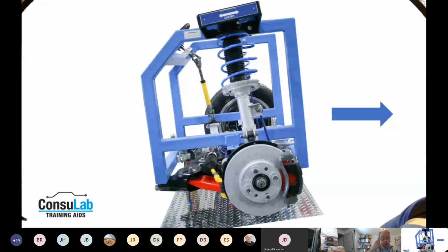Same in this case here. If we've got the frame angle down in the rear, we're going to end up with more caster than desired. So in the case of this, with a frame angle down in the rear, we'll actually subtract and maybe work towards the lower end of the caster. So there are compensations that need to be made as we're doing our alignment.